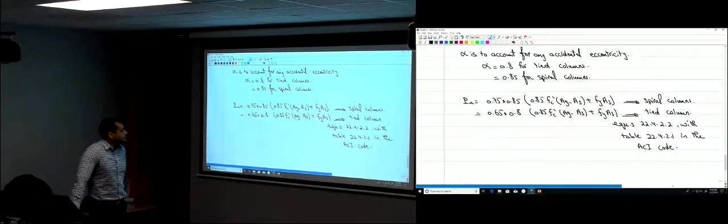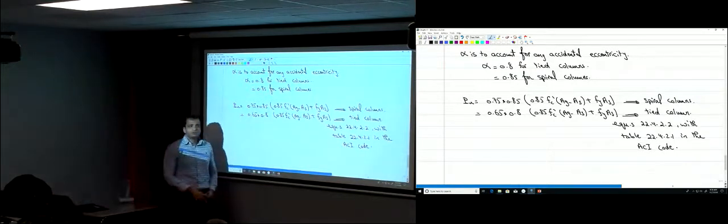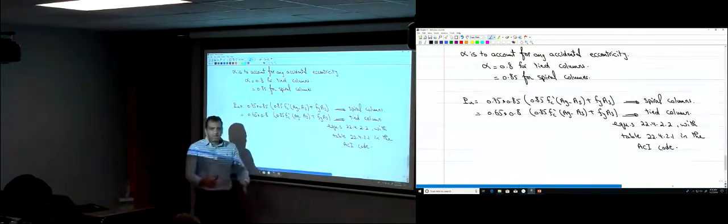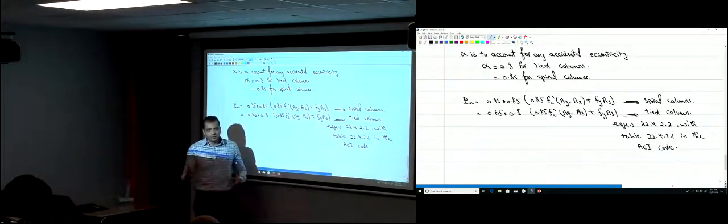So that equation will allow you to design your column. To design the column, you need to find its dimensions and the amount of steel to put in it, right? So you only have one equation that has those two parameters. Area gross is the area of the column, and area steel is the area provided by the steel.